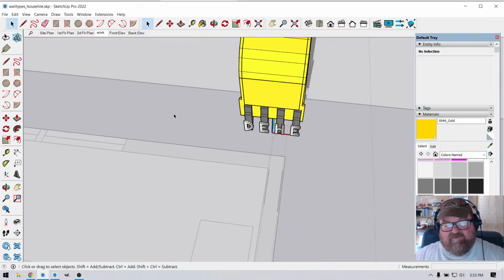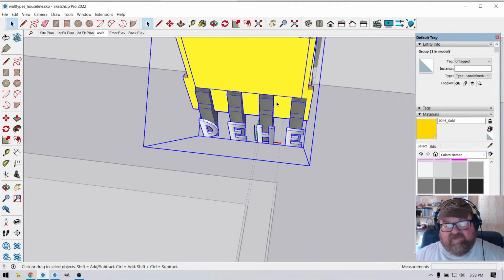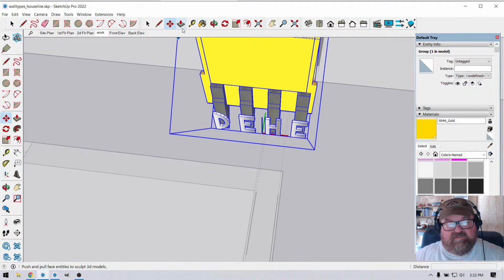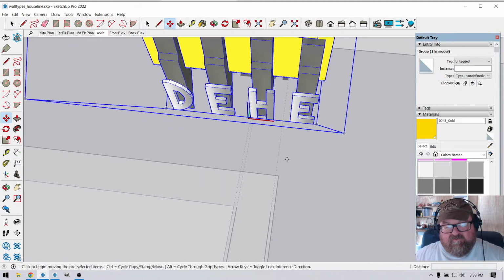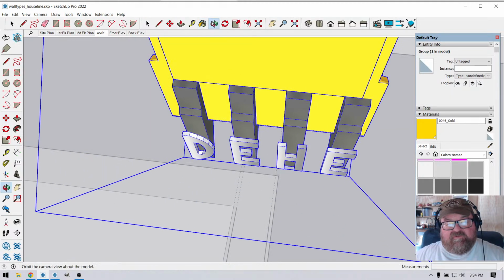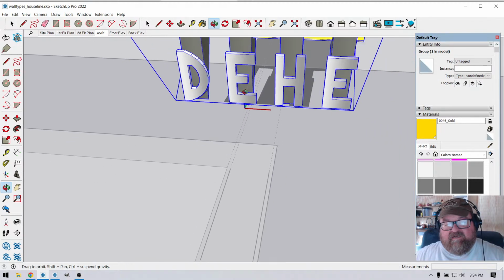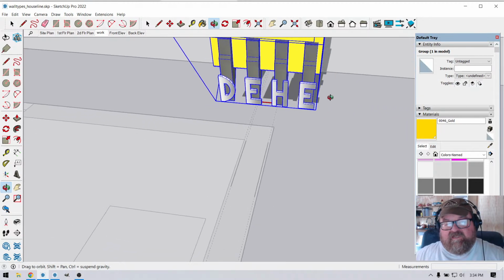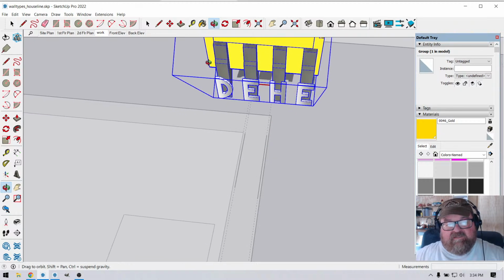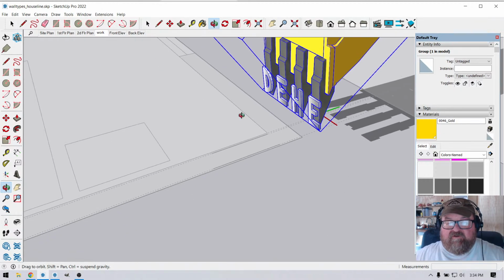All right, we're gonna talk about this anyway. When you're out laying out footings, you'll tell the guy to dig two teeth outside the line, or 3 teeth. Usually I'll look at his bucket, and it's usually 2 or 3 teeth. And you'll dig the footing bigger all the way around, right?